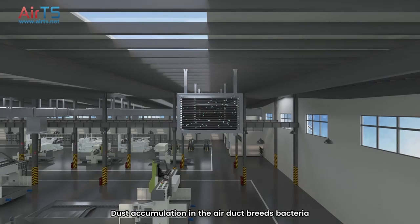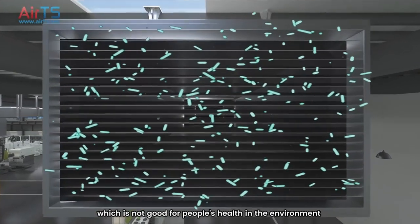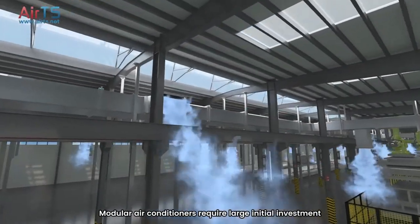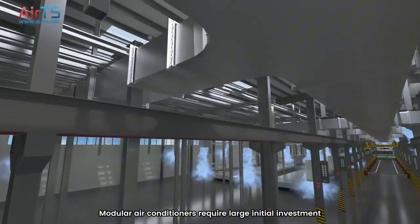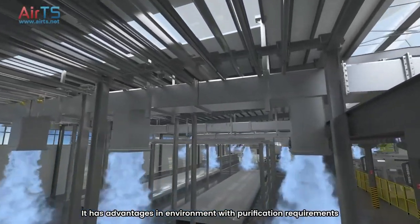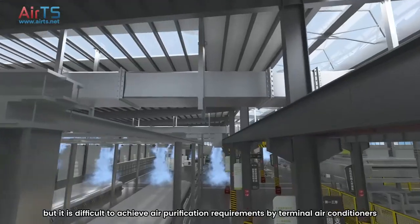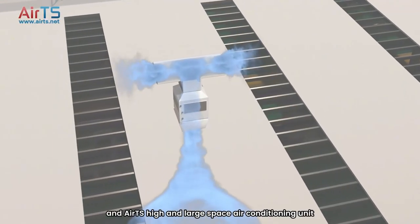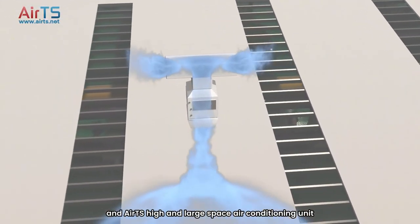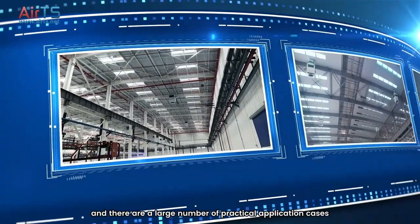Dust accumulation in the air duct breeds bacteria, making it difficult to clean, and the quality of the air output decreases, which is not good for people's health and the environment. Modular air conditioners require large initial investment and high subsequent operating costs. It has advantages in environments with purification requirements, but it is difficult to achieve air purification requirements by terminal air conditioners. Fresh air function can be introduced, and AirTS high and large space air conditioning units have matching fresh air unit series products, and there are a large number of practical application cases.